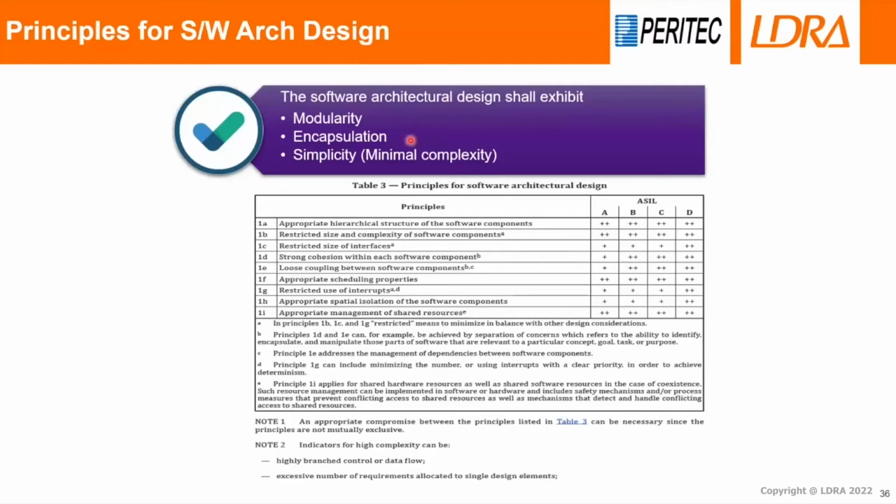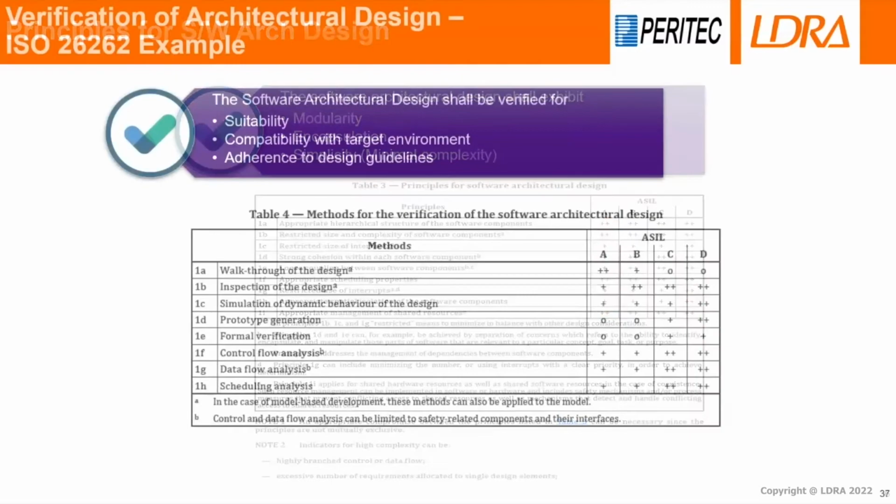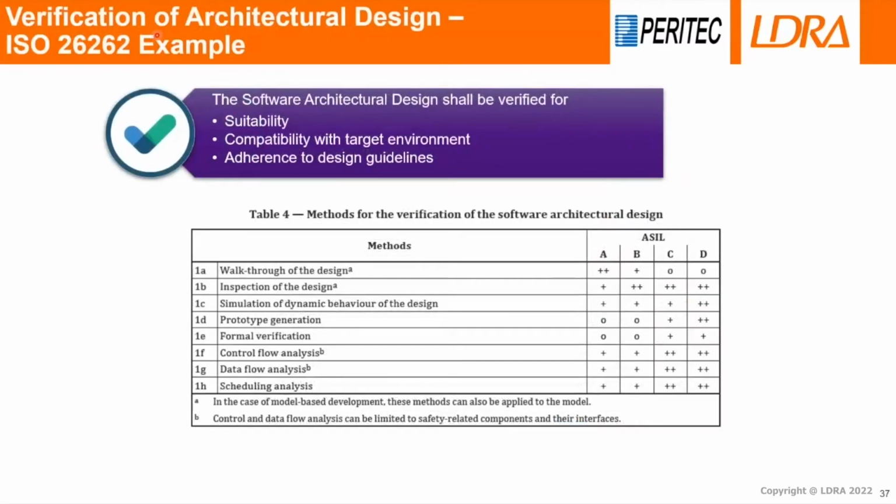It also gives a table which lists a lot of design principles, and most of these design principles are highly recommended for ASIL D, highly critical applications, and for less critical applications there are a few recommendations. Looking at the verification activity for the design, you can see simulation of the design is a recommendation, but it is highly recommended for ASIL D. So if you have modeling tools, you can do the simulation.